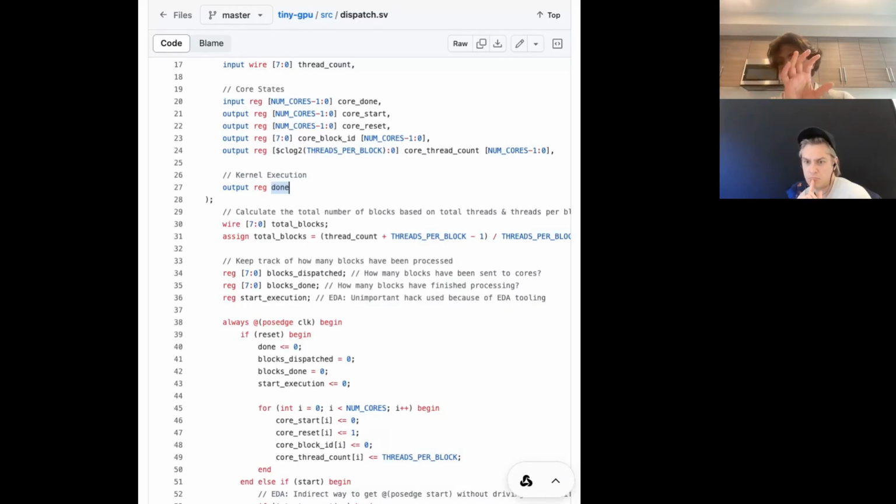And then those gates are based on a specific process node. So basically, you have these things called standard cells, which are specific gate designs for a specific foundry's process of producing gates. So you convert them into gates, and then you lay out all these gates on a huge chip design. The gates are laid out everywhere, all over the chip, based on a bunch of different optimizations. Then you hook up all the gates with wires, the gates that need to be connected together. And then there are several cycles of optimization on this whole process to make sure that everything is valid, all the timings are valid, because electrical signals need to flow through this chip. And if any of the signals flow through the chip slower than the actual clock time of the chip, that's going to cause an error.